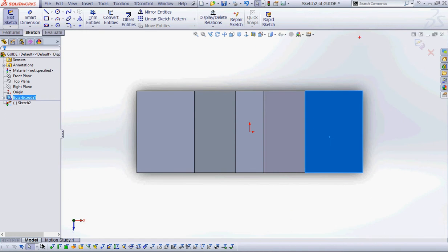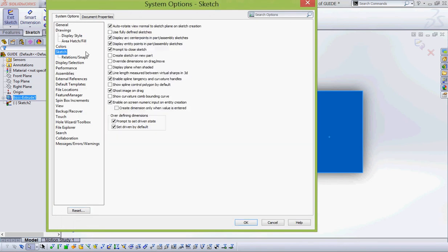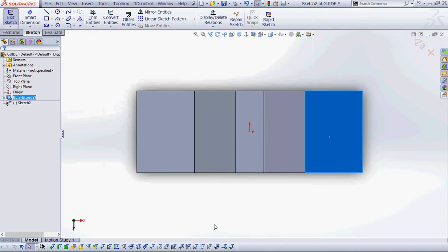And the total length here, the 30, that's the total length. So that means it's 15 on one side, 15 on the other side. SolidWorks automatically does the math for you. It just wants the total, and it knows if you're doing a mid-plane to just divide it in half on both sides. And then you want a green check. And notice, if I look at my front plane, my front plane is right in the center of this part. Do you see that? So that's nice. And I'm going to save it.